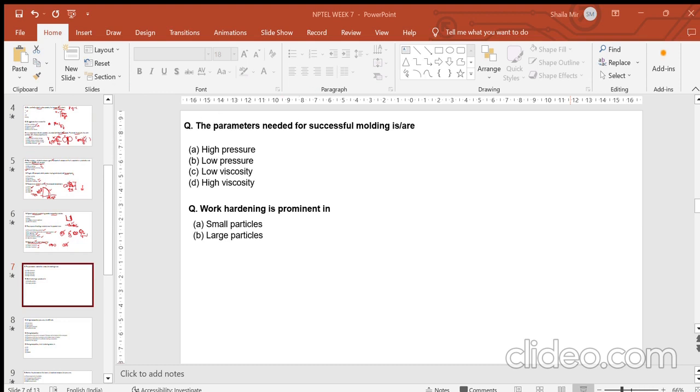One point is that the ball mill does not run with 100% loading capacity, right? It is always 30 to 40% loading. Maximum 30 to 40% loading happens. That means the rest of the space inside the mill is free. Also, out of the 30 to 40%, there is the charge that is being used: the material that you are milling, the powder, the feed material, and your balls.